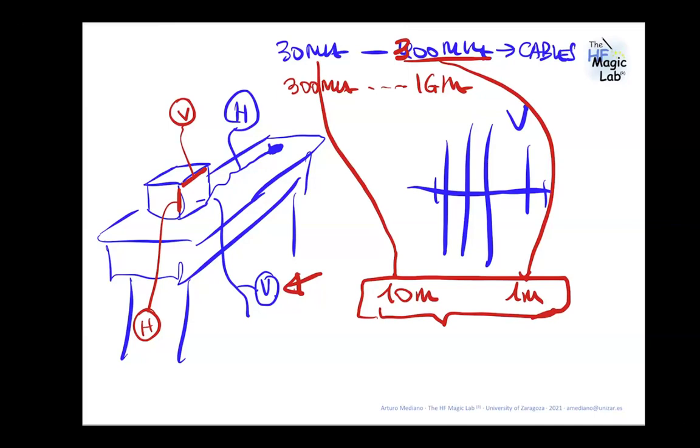Obviously, if you want to identify how much current you are injecting in the cable in common mode, you need the factor for the current probe, so you can convert volts to current, to microamps or something like that. With the antenna it is the same. You want to identify how many dB microvolts, but in debugging in your laboratory without a sealed chamber, or with some limitations, what you want to see is what happens if you change the software, add a spread spectrum, put a ferrite, or move some specific part of the system, to see if you reduce 3 dBs, 10 dBs, or 40 dBs. Great, thank you.